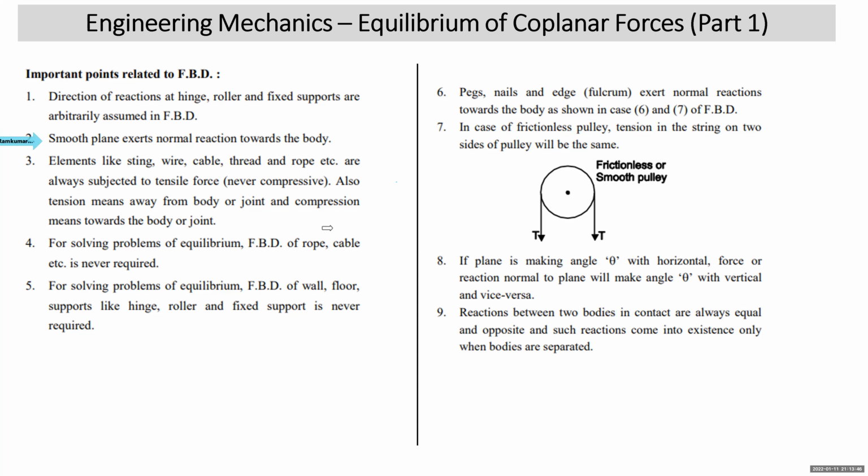In case of the example of sphere, we understood it. Next, elements like string, wire, cable, thread, rope, etc. are always subjected to tensile force, never compressive. You should remember it for solving the problems of statics. And tension means what is away from the body.